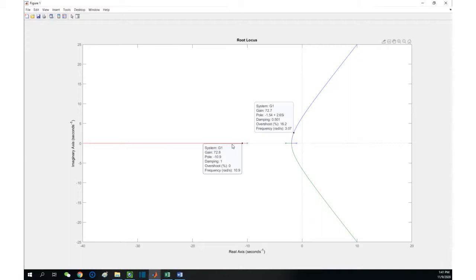And there is no overshooting. Does it make sense? So it looks like a first order system. Right? And why would there still be a frequency present? Well, you still have frequency, of course, but it means nothing. You don't even have oscillation. So we just disregard the 10.9 frequency in radians per second because it's not complex, right? Correct.